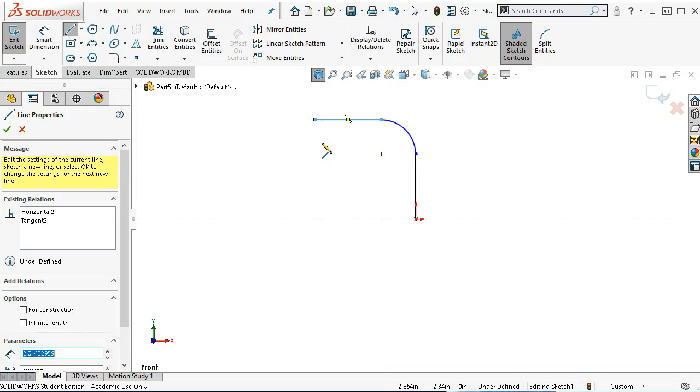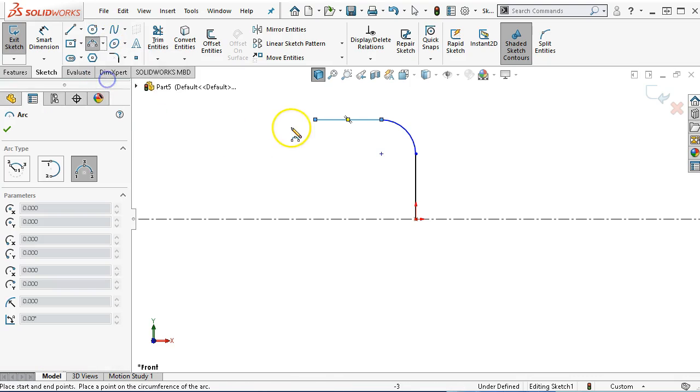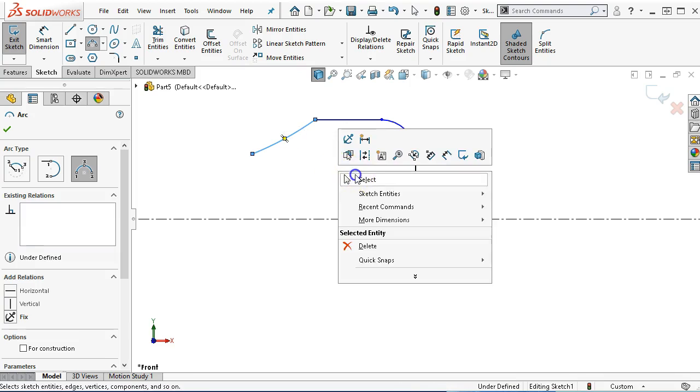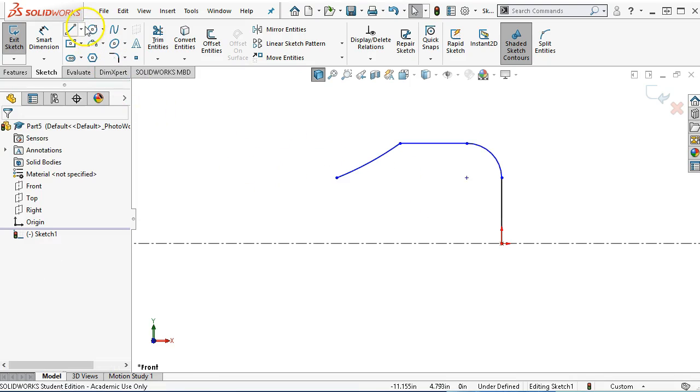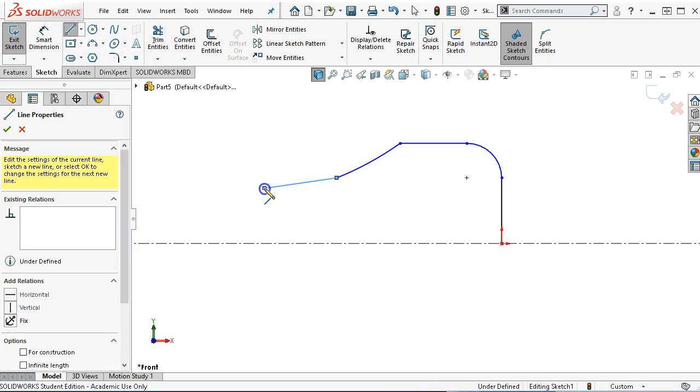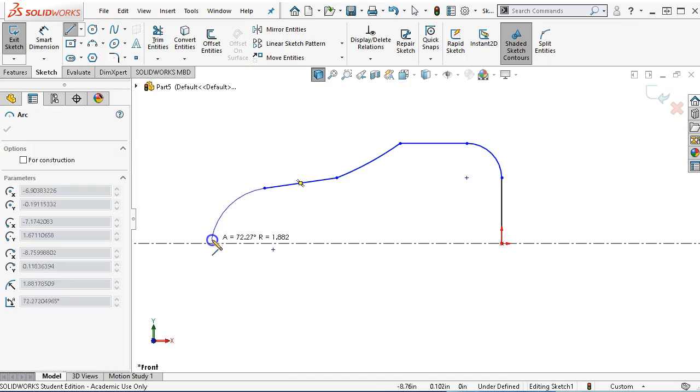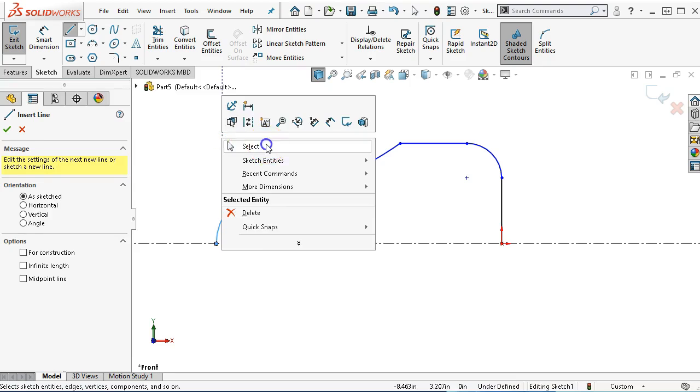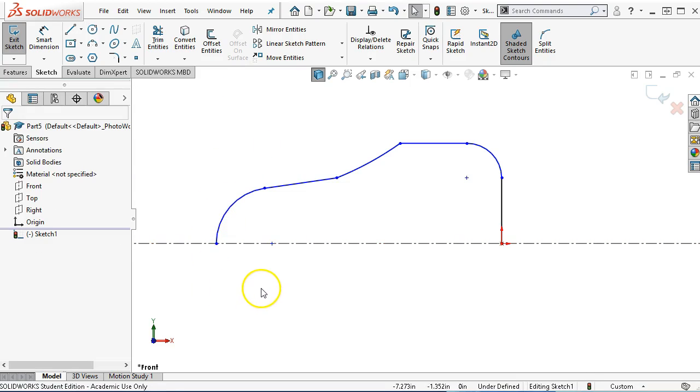Now this arc isn't going to be continuous. Coming off tangent is going to bring it down in more of a swoop. So I'm going to switch arcs over to the 3-point arc so that I can control it a little bit better and get that swoop, more of that result. Alright, so then we're given a line off of that point, and then I'm going to do the continuous arc back to the center line. So again, I don't want to make the full arc, because when I mirror it, it will mirror onto itself, creating a duplicate entity, and that's not a preferred result.